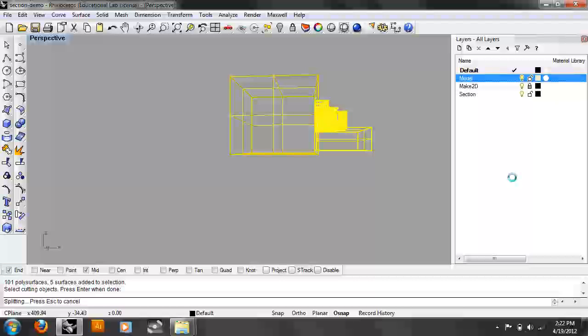What's a third, like nuclear option that we could do to actually cap all those things? What could we do if we had all the time in the world and infinite resources? Just redraw. Yeah, you could take a line tool and draw over the edges of it and then make them planar surfaces. Which, for your models, guys, might work. You may not have very complicated models, okay? Maybe not Unity Temple grade models, right? Not yet, at least. Are you rendering these sections? I'm going to. I'm going to show you.